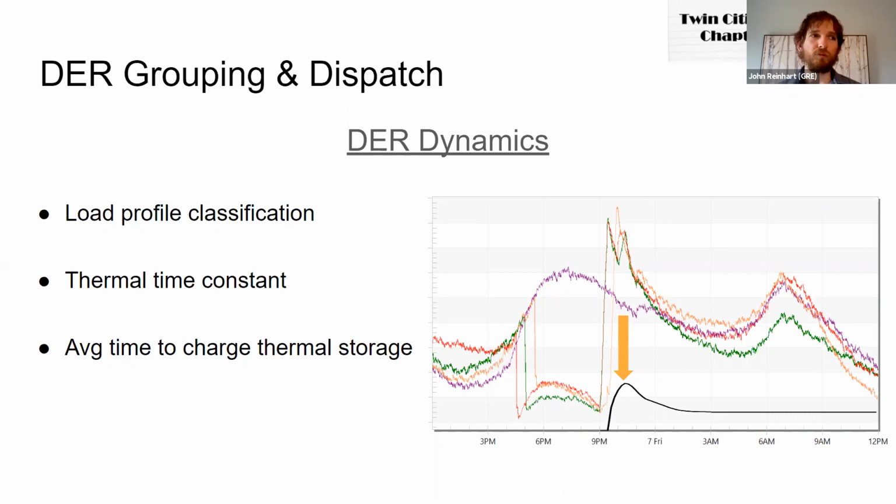That might help a building management system, if you've got a variety of different loads with these different characteristics and you're responding to an instruction from the utility, to stagger or stage these things in to smooth out your building's response, manage your local peaks and provide good grid services.